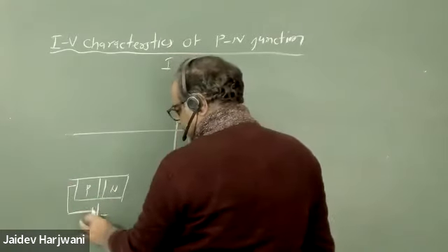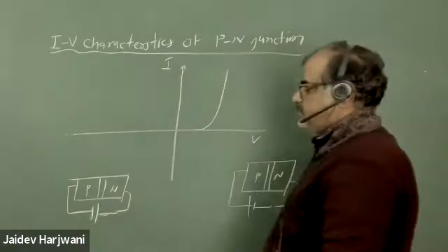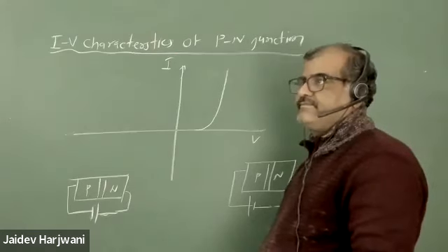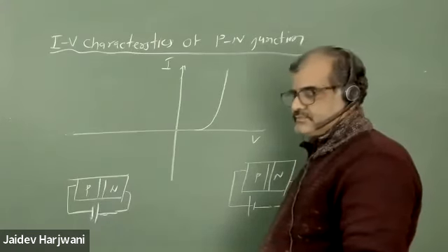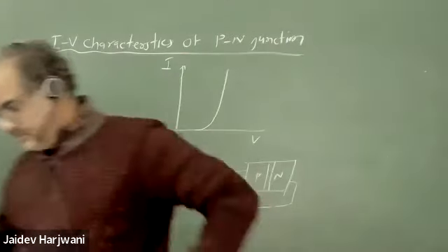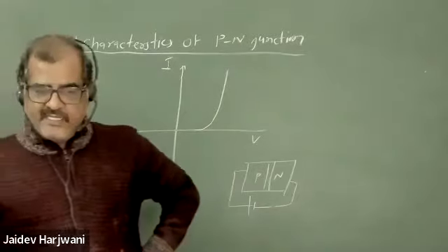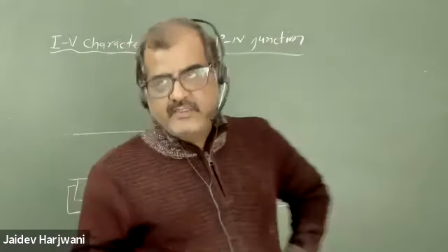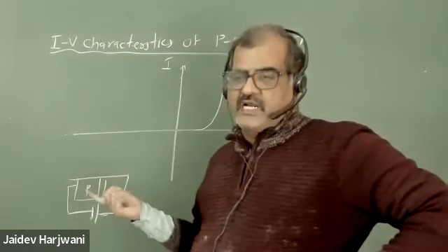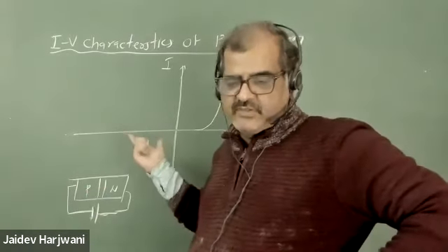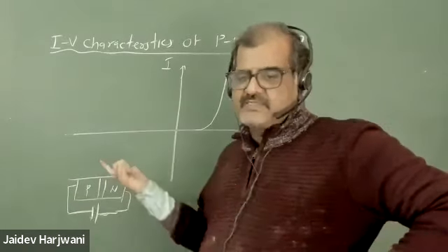Sorry sir, in what we did previously, when we calculate this Cj, the silicon epsilon S upon W is coming, meaning this is coming like Cj per unit area, like Cj dash is coming, right? Here it is Cj. Here area is not there, na. Here we have already been given the charge density. So when we calculated the charge, we just integrated that one. So area was not there. So here you just calculate the capacitance Cj.